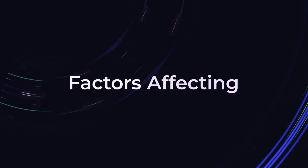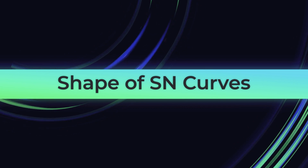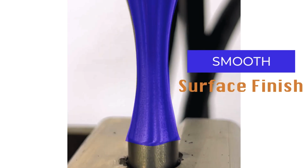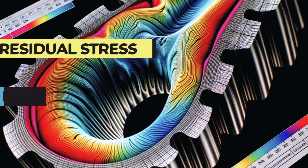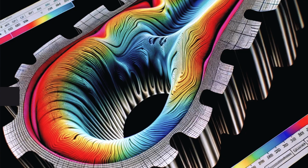It is important to note that the shape of the SN curve can also be influenced by various factors such as surface finish, environmental conditions like corrosion, temperature, residual stresses, and loading type. For example, tension, compression, which we will see in the future sections. As a result, when designing components for fatigue, it's crucial to consider the specific conditions the material will be subjected to. We'll explore all these in more detail shortly.